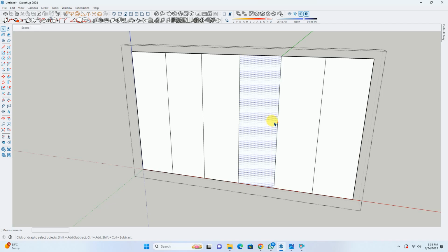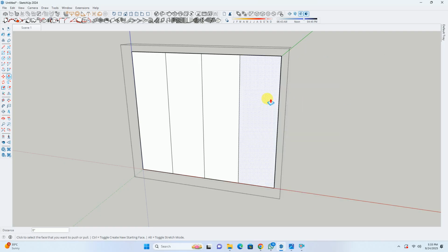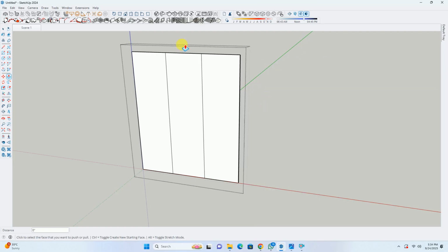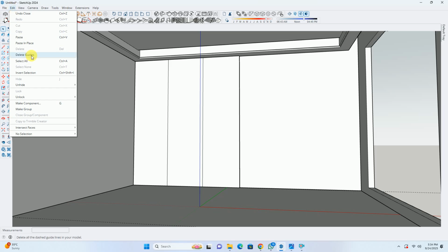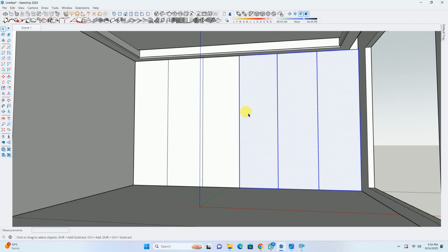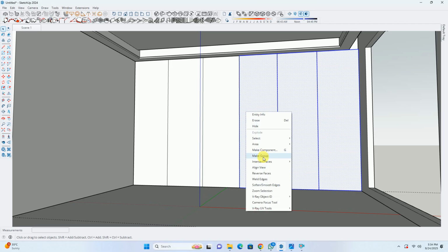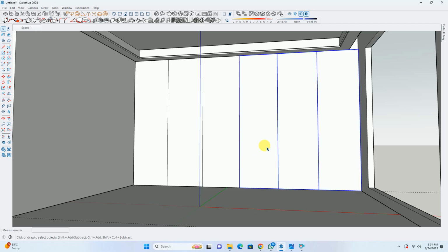So I'm going to copy these surfaces. I'll apply the Control C command. I'll remove these surfaces because this paneling would be of different material and the right side paneling would be of different material, right? So I'll remove these surfaces and press escape. Then I'll again go to the edit feature command, go to paste feature, right click on these elements and convert them into a separate profile.